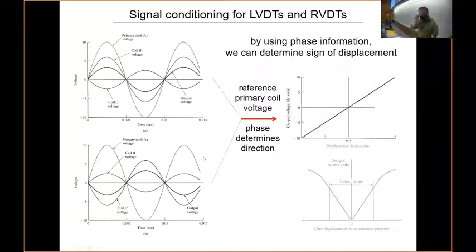And this is kind of idealized here. It's showing your output is perfectly in phase with your input. You're going to see small shifts even in that, because you're going to take your output of the function generator and you're going to split it. And part of that you're bringing into the oscilloscope. And then you're taking the output after the LVDT into the second channel.